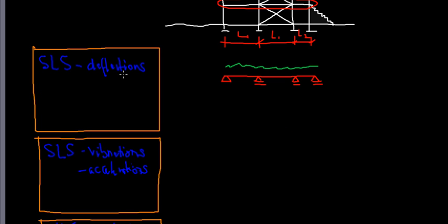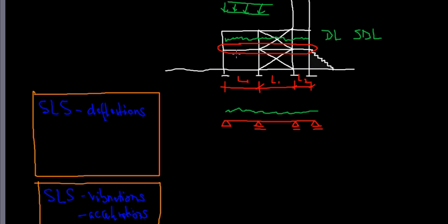So what would be problematic here if we had deflections that were too high? Well, the reason we limit deflections is if we had partition walls here and the slab would really deflect a lot, the partition wall may crack or not stay in place. If we would have a curtain wall, a facade on the outside, and the slab deflects too much, maybe the joints will lose their water tightness, their air tightness, and we would have system leakage. And also, of course, if you say have a party and the slab deflects too much, it may scare people or everything rolls to the middle of the floor. It's basically no longer a good serviceability state. That's why deflections want to be limited.